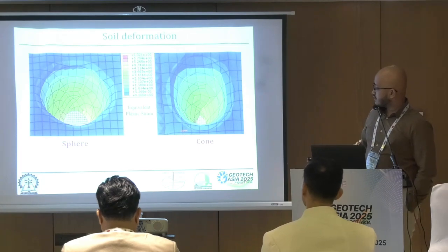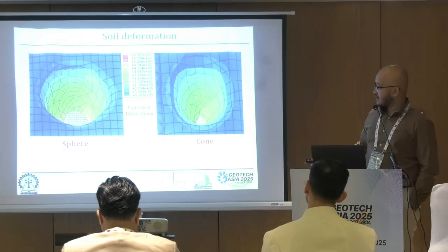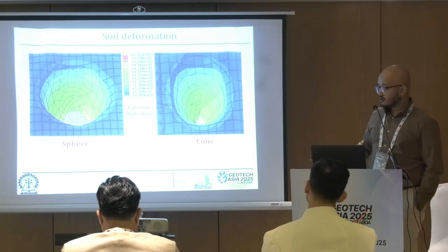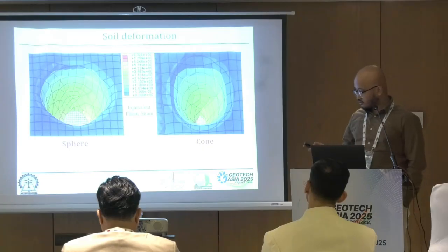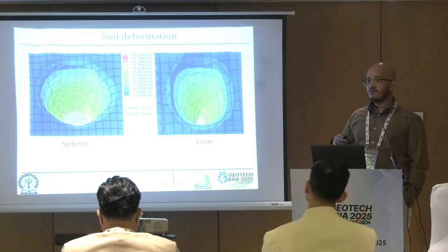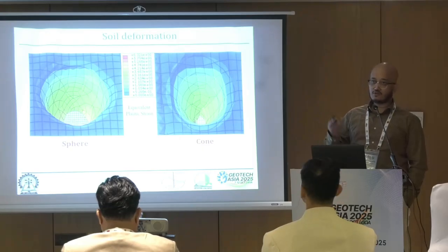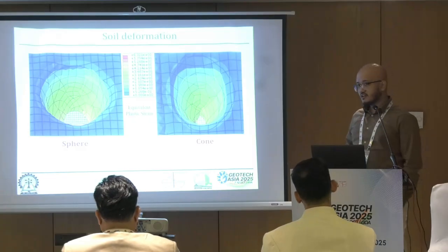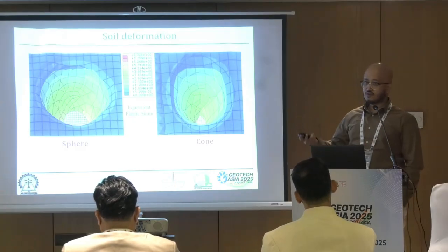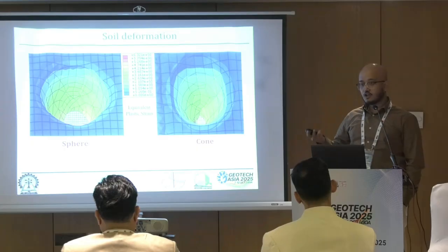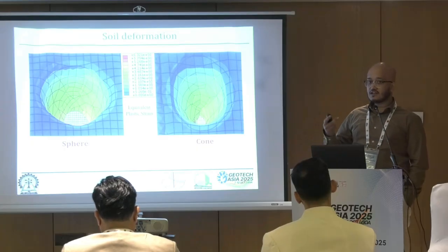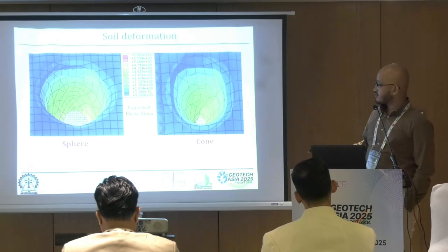And then you can see a gray part at the bottom which shows the exposed pipeline part. So it eventually gets to hit the pipeline. Why is this another part important for this study? When we are doing this study on an exposed pipeline, we already know what velocity it is going to hit the soil with. But when the pipe is buried in the soil, we need to track the movement of the object through the soil accurately. Only then will we be able to capture the exact velocity at which it will impact the pipe.